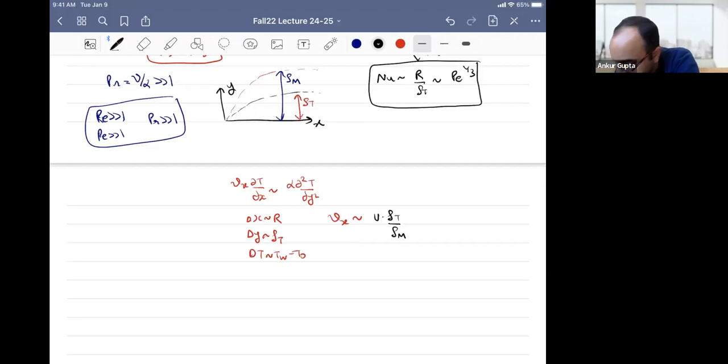We know it scales as R times Reynolds number to the power of minus half. We had discussed that delta by L goes as Reynolds number to the power of minus half. That's what I'm recalling here, noting that the length here is the radius of the sphere. Any questions here?